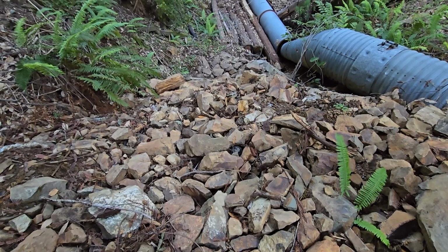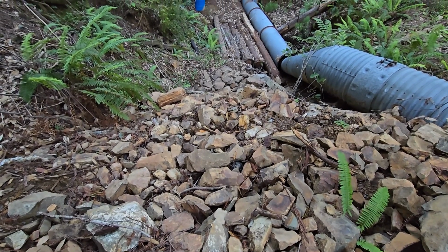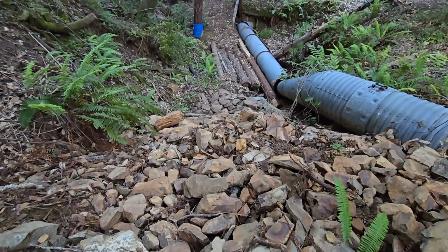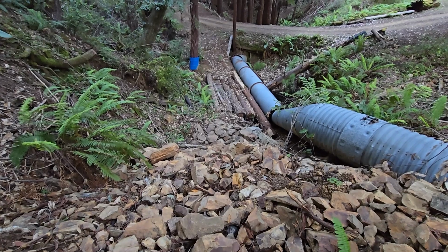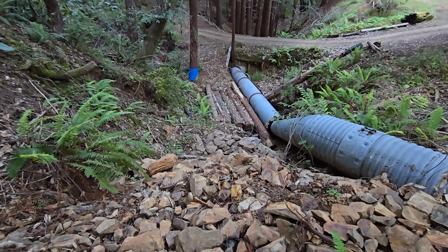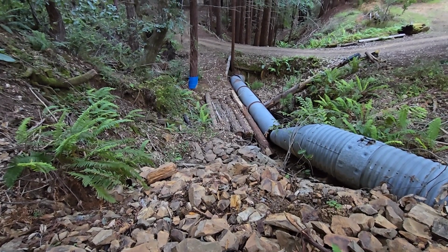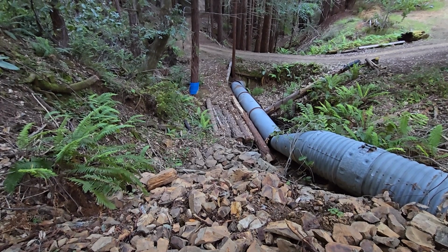Dan used fractured angular rock that was mixed in size from 6 to 12 inches in diameter to armor the spillway. Because this rock fit tightly together, it was less likely to move during a flood compared to using rounded river rock. The project took 4 weeks to complete.